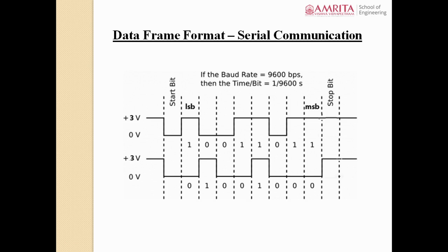By default, both the TX and RX lines of LPC2148 will be pulled up to VCC. In the case of LPC2148, you have a 3.3 volt VCC. So if there is no transmission or reception, both the TX and RX lines will be pulled up to VCC.